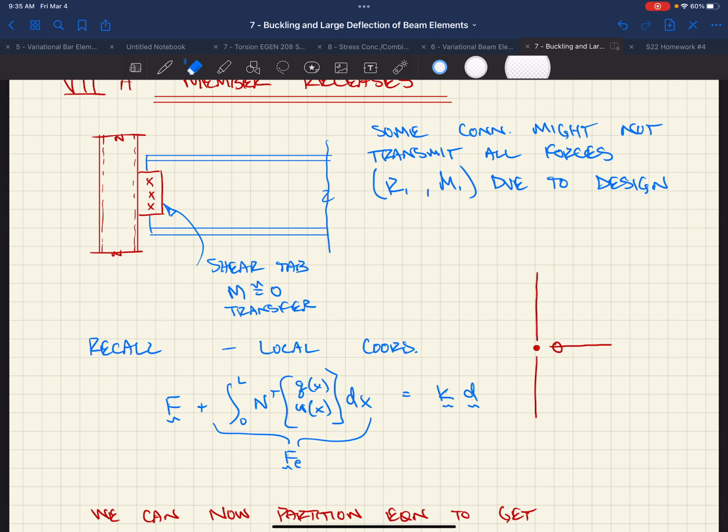So I was just trying to make sure that it was doing this properly. Yeah, the idea is that it's based on the connections and how you decide to design it. If they were tube steel knee braces or something, and you welded them all the way around at the end, you've got a lot of moment transfer there. And I would say you probably should make that fixed.